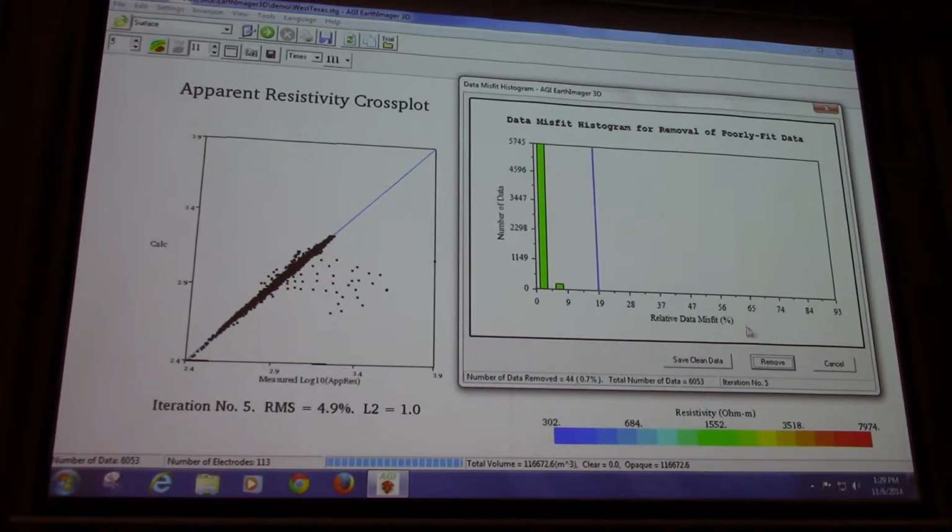So when you're moving it over right now, it's doing what? It's eliminating things that are far away from this diagonal. Okay, so anything that's not fit. This means that the measured apparent resistivity is much greater than the calculated resistivity. Because if it's one-to-one, this data point would actually be up here. So that's something misaligned. Most likely what happened was not an error in the calculation. The error is here. This data point has to do with the voltage and current that we measure, right? So that means that the voltage was measured wrong.